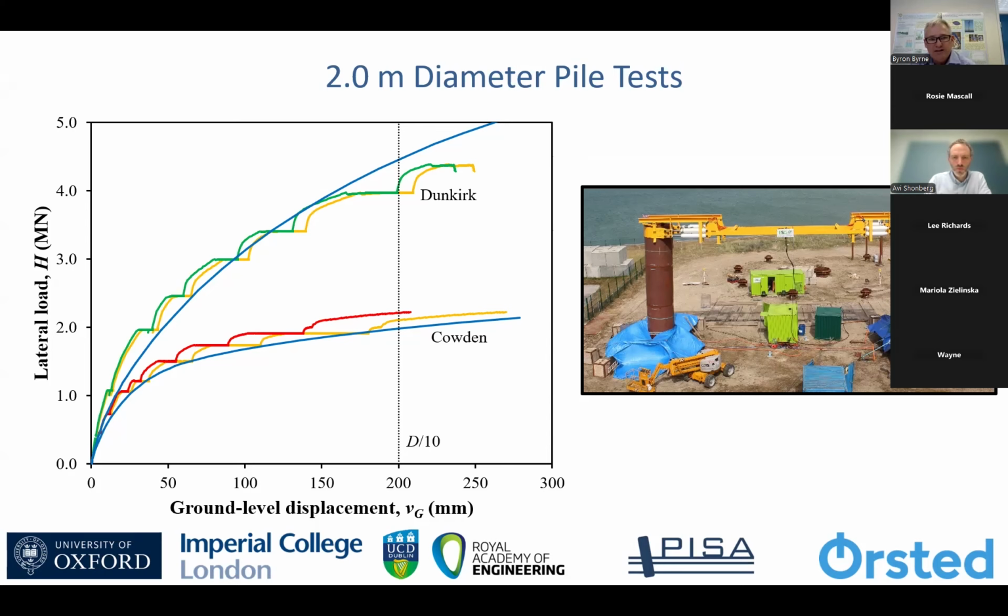And then in blue, these are the finite element calculations that were computed prior to the field testing. So they were computed in advance, and you can see there's a very good match between the computation and what we achieved in the field. So this gave really great confidence that well-calibrated and well-performed finite element calculations could predict field behavior. And with that confidence, you can develop your more simplified models on the basis of results from the advanced numerical modeling. So that is the PICASO project, and now this process is widely used across the industry to design offshore